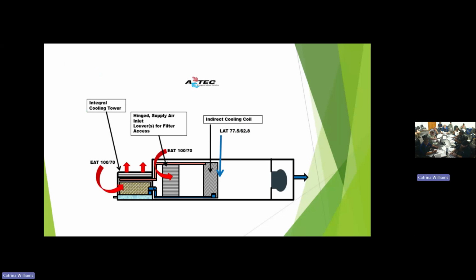Well, here's how the system works. You've got a cooling tower that water pumps through, and we cool the water down through this, just the same evap media that we use in the direct section. But if the water runs through there, it cools off. So then we pump it back over to a cooling coil.